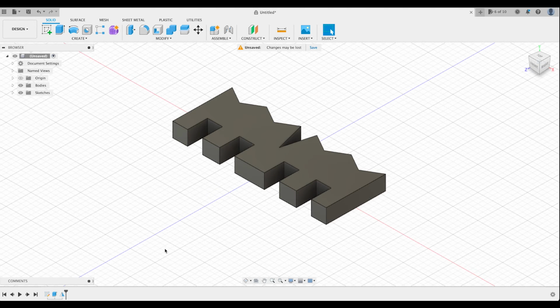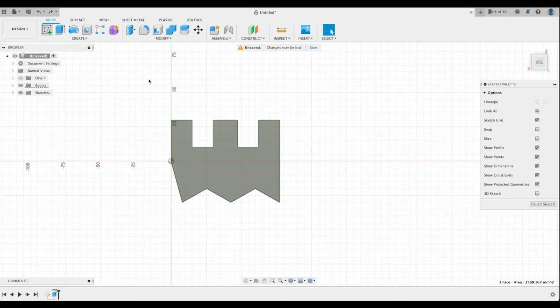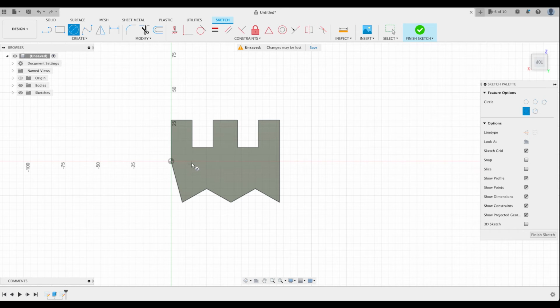If I undo that, and let's see, we wanted to do some functions on here. So let's say this is half of my object. Let's say, for example, I wanted to now click on here and I wanted to add something. Let's drill a hole through here. We've got a couple of holes that we want to drill. So I'm just going to do this quickly. Let's make a 9mm hole,